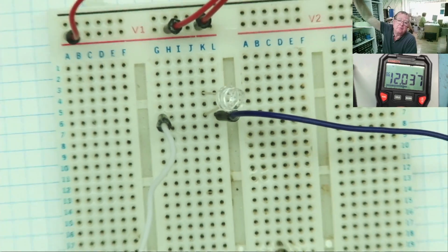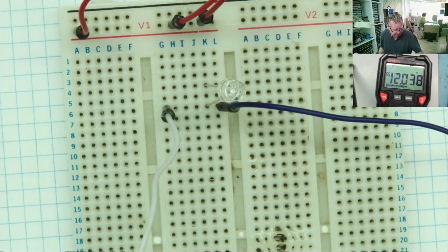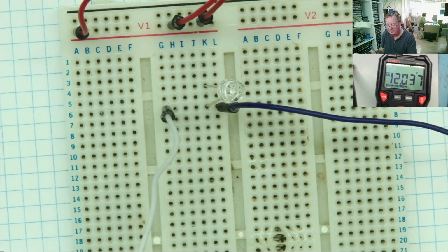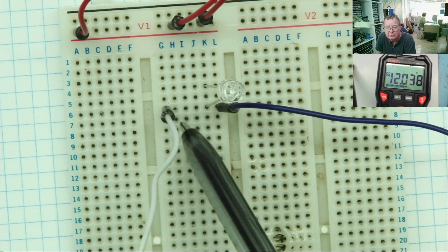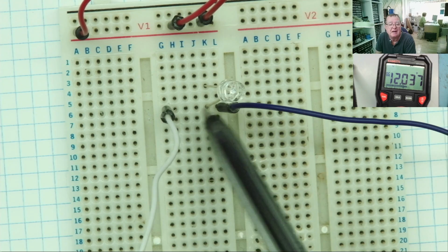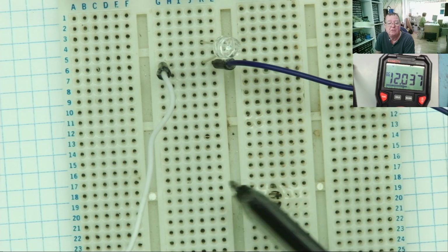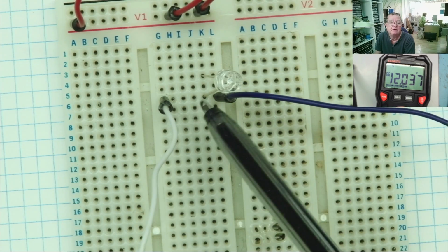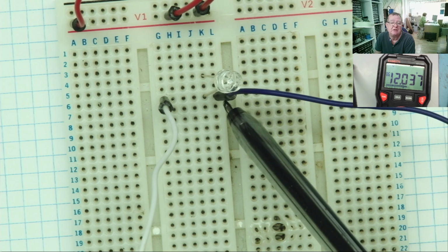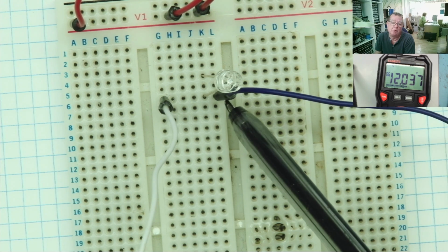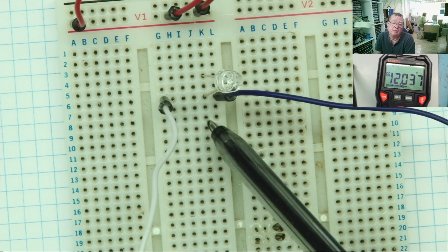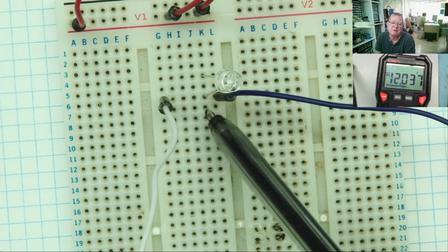These breadboards, by the way, if you're not familiar with them, just briefly, each strip of holes, 6 holes, is connected together. In fact, you can see, because this one's burnt, there's a set of metal clips which runs across here under each set of holes. So effectively this is the negative supply, 0 volts, ground, however you want to call it, we'll talk about that later as well.